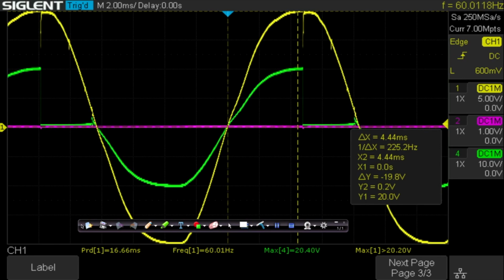That's currently connected to the anode of the diode. So channel 1 is measuring just the straight up AC voltage. Channel 4, the green one, since I have a 4-channel scope, is connected up to the anode, so it's measuring the anode to cathode voltage.